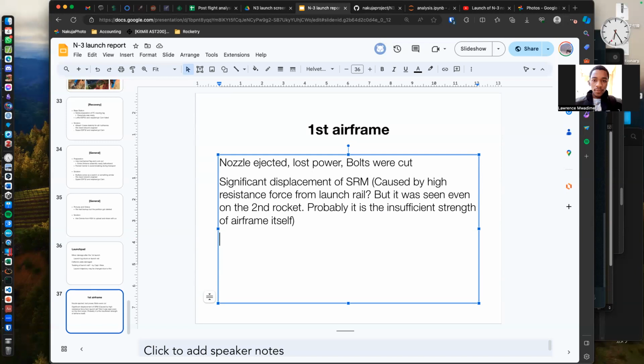We found that after that, all the rails were smooth. It's only the last launch that left a single lug, but all the others went away with the lugs. So as a proposal, we need to ensure that the airframe is stiff and strong enough to avoid any tear on the skin due to shear of the mounting bolts or screws.